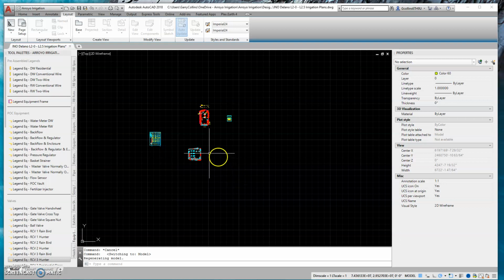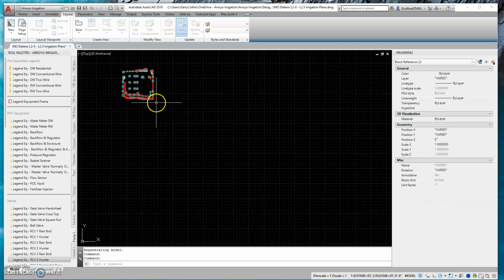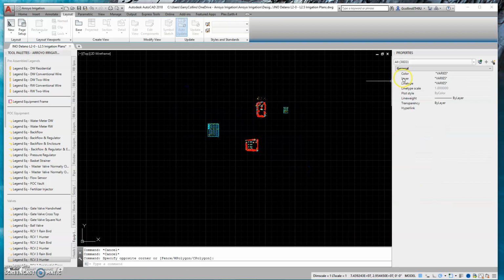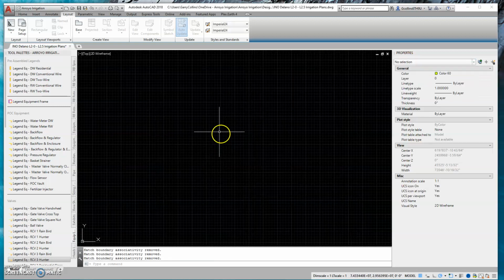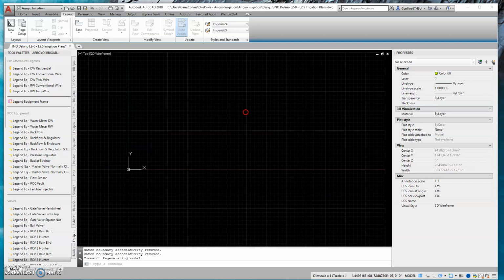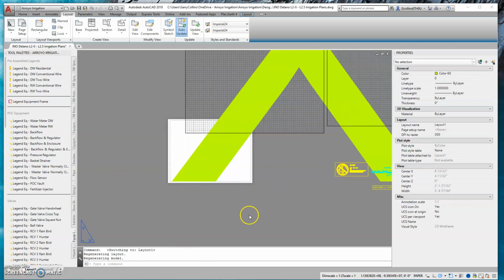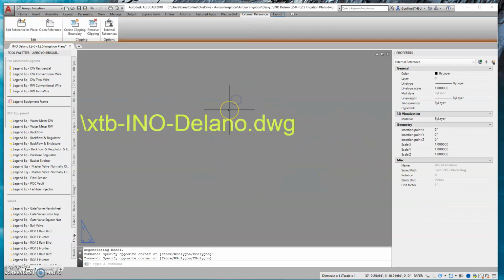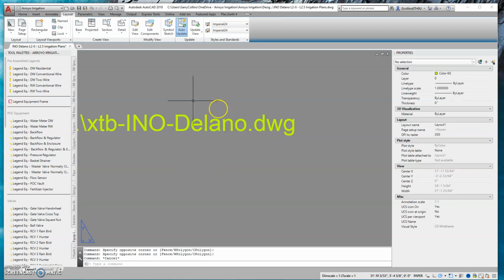One of the things, see, this is all in model space, right? Yeah. We don't want that, right? Yes. So the biggest thing is we come through and I delete everything that's not the XREFs. That's one of the first steps I do: I delete the model space before I path the XREFs, because now the XREFs aren't showing up. They just list the link. As long as I don't delete this, once I relink it, the XREFs will show up.